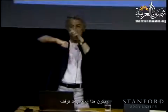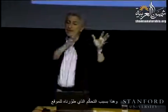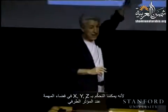I'm sorry? Doesn't it just stay where? Well, if it is 0, it is basically free now. That spring is cut. So you move it, it's going to move. So from the control we developed for the position, because we have a control in x, y, and z in task space, the end effector is stiff in this direction, stiff in that direction. In this direction, if you change kp and make it 0, now it's free.